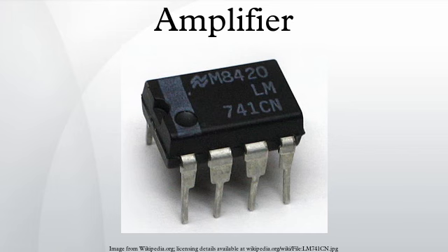All amplifiers generate heat through electrical losses. This heat must be dissipated via natural or forced air cooling. Heat can damage or reduce service life of electronic components. Consideration should be given to the heating effects of or upon adjacent equipment.